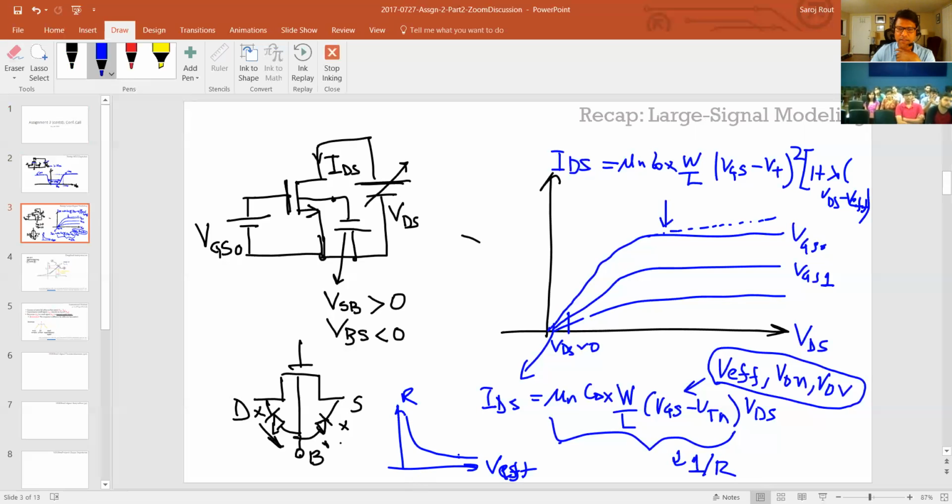But at every point here, like you choose a certain V effective, these points here are actually these lines here. So they're linear as long as you have VDS equal to 0. So I'll show a problem towards the end. I think pretty much everyone missed that problem, the 1.22, which shows the bandwidth. That's actually perfectly in a linear region because the VDS is almost 0. So you'll actually use this equation.